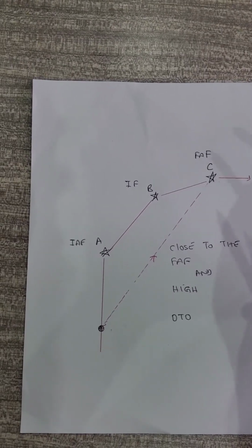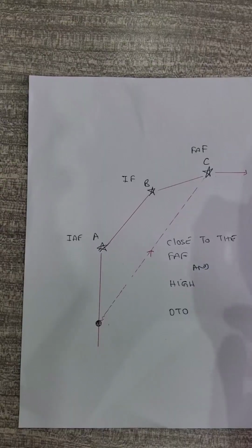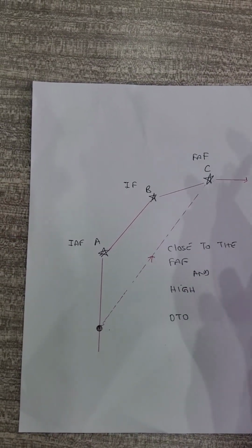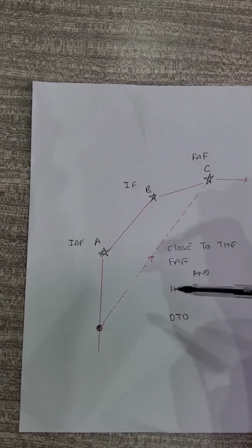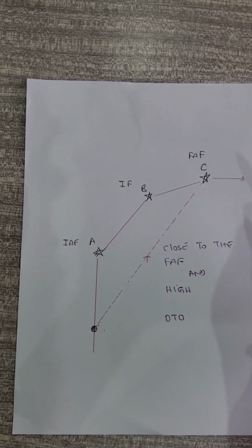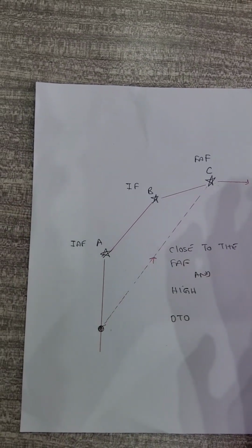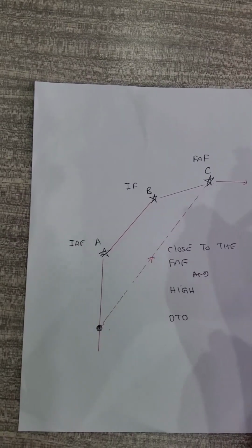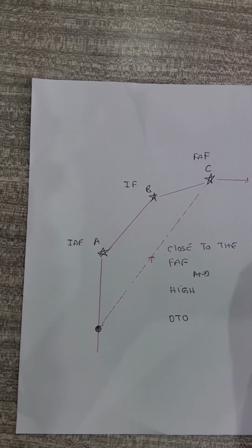This is where I'm going to show you on the video that I just made today regarding how to program the FMS. It's a very simple procedure. The first thing you do, you should not be in VNAV. You are in VNAV, all this is LNAV VNAV, but you have to disengage VNAV, and to do that you disengage VNAV by pressing vertical speed. That will be the mode that you'll use.